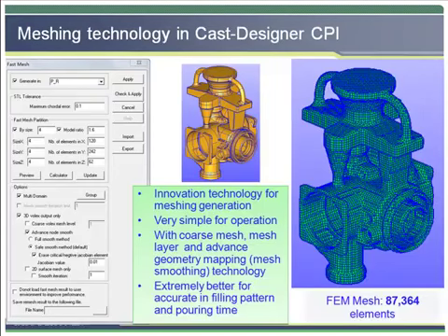We pay a little more attention to the meshing process, since it is always a critical issue and argument between FEM technology and FDM or FVM technology. Cast Designer is using FEM technology. It is more advanced compared with traditional FDM or FVM methods, because of the good geometry description, better formulation, fully coupled simulation, and flexible memory management. All of these are very important for casting.